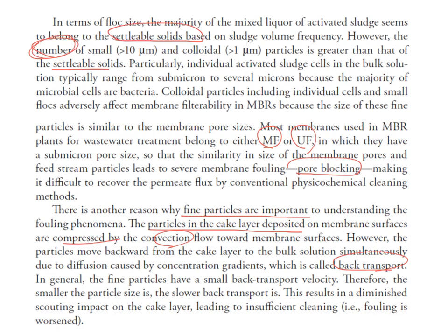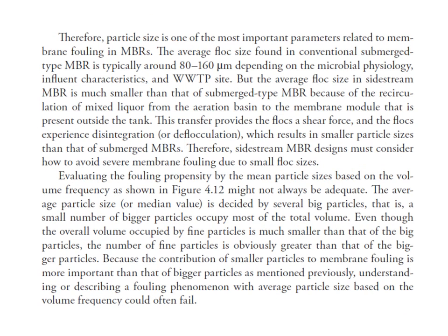This results in a diminished effect of cake removal, which will eventually lead to insufficient cleaning. Therefore, particle size is one of the most important parameters affecting membrane fouling.